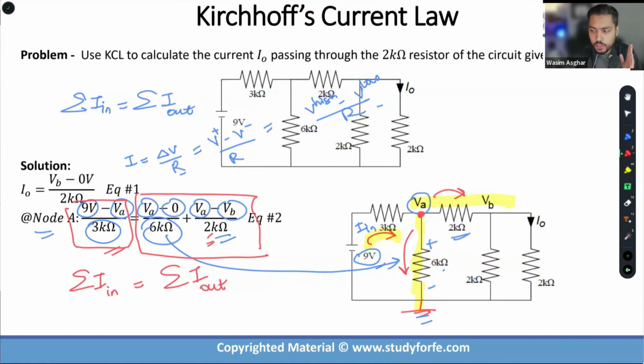Remember, it is not required, it's not mandatory, it's not a prerequisite that you hit the bullseye with your assumptions, that you don't have to make any adjustment at the end, right? The requirement is only that whatever you assume has to be consistent with your equations. Your equations should basically tell the picture that is in your assumptions on the circuit, and your circuit should paint the same picture that is painted by your equations.